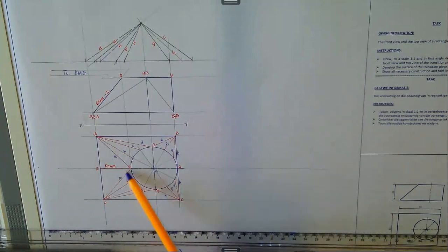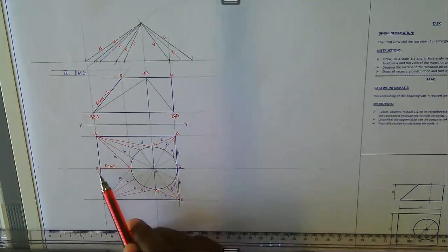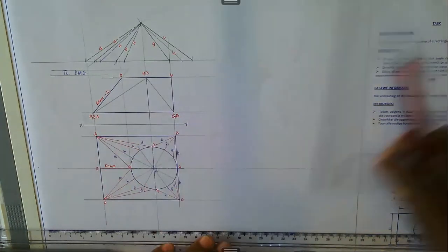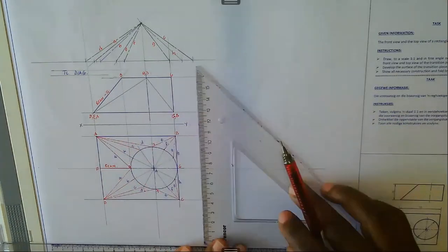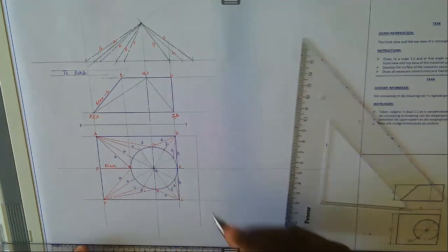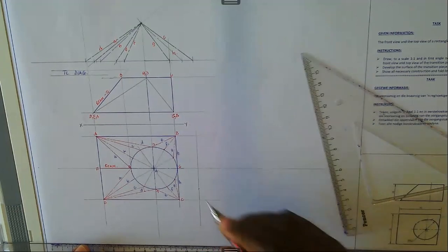Now, once you have done this, the next thing that you require is to come up with the drawing in terms of the development, right? This is our seam line from 0 to E, which is already a true length. So if I were to start somewhere here, just draw a line like that and say this is my point 0.